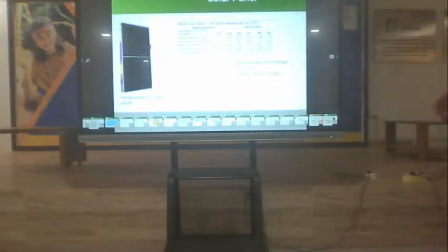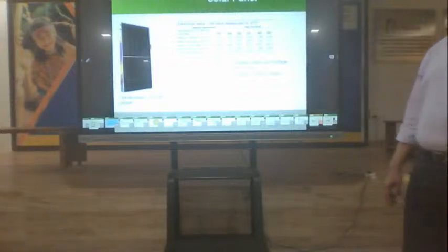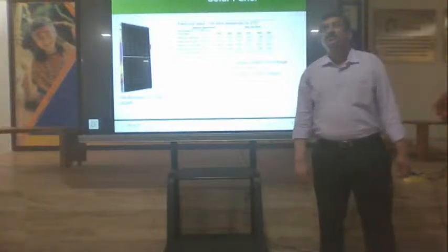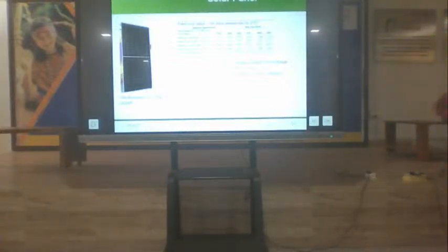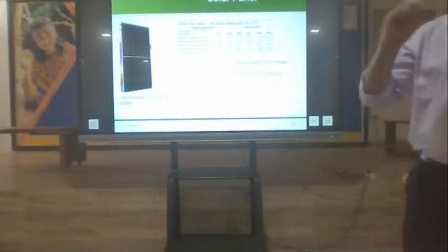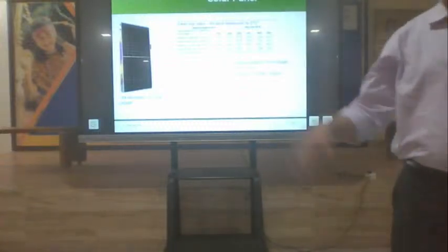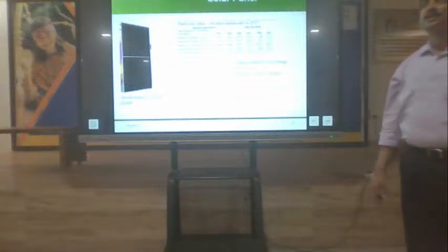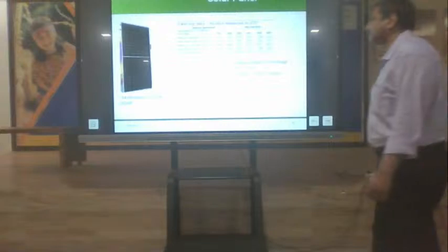So what an MPPT converter is, maximum power point tracking, is nothing but a regulation of this voltage. From the dark mode to the lighted mode, and from the no load to load, in between these points, the DC-DC converter adjusts the output to the maximum power point. That's why that regulator is named MPPT. So basically, for solar, you use a DC-DC converter that is called an MPPT tracker or MPPT regulator converter.